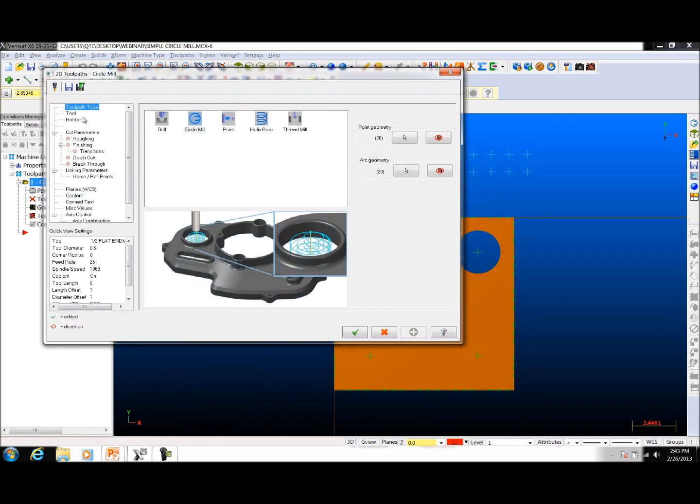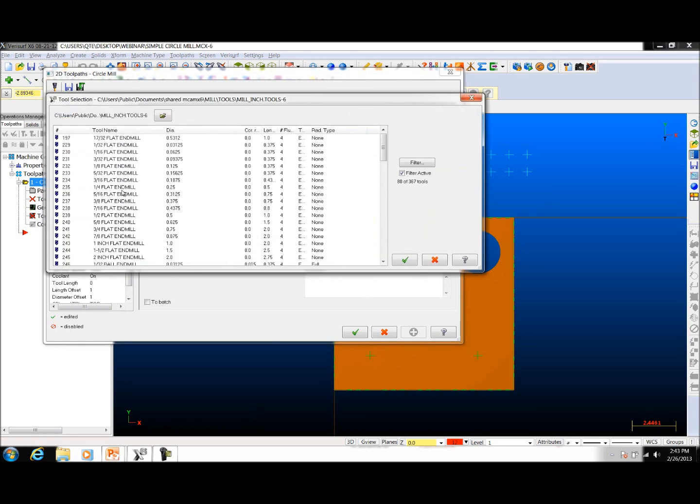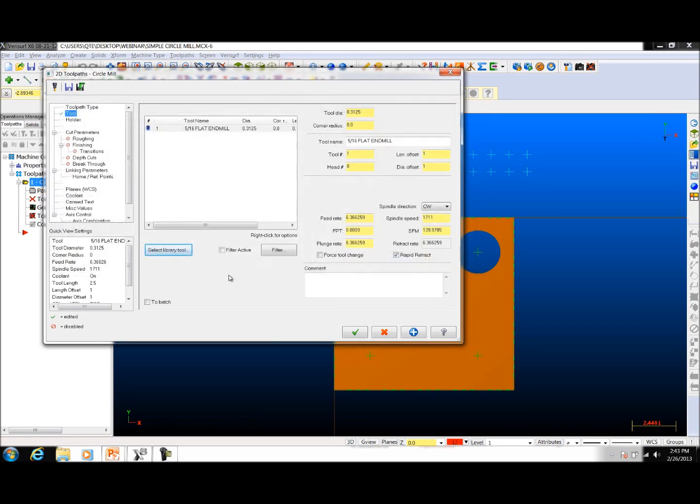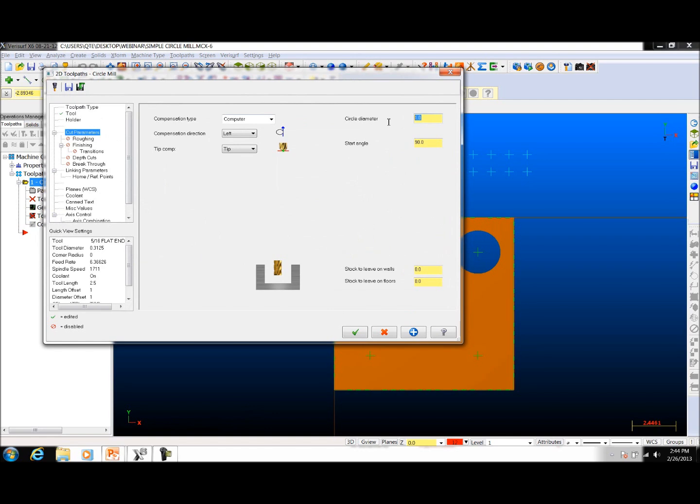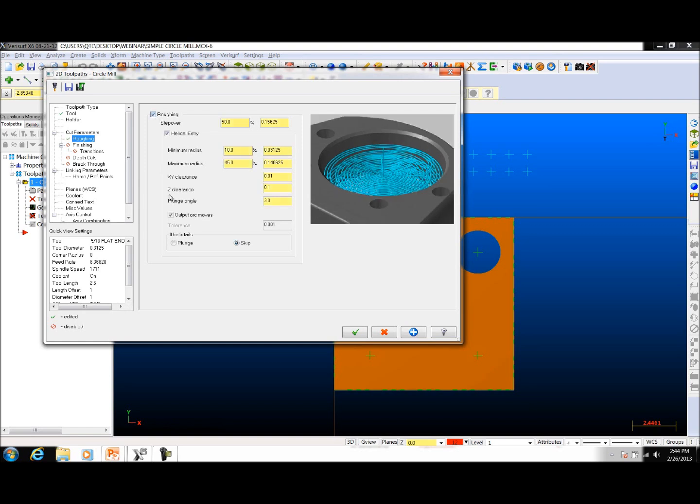Okay? Go pick a cutter. Now since there's no geometry there, it just has a location, I have to fill out every parameter, meaning what's the hole size? 750, 875, whatever the print requires. Now you can rough it out. Now if you use roughing, it'll use a corkscrew type spiral motion, starts from the center and climb mills to the edge of the hole. Okay, this is your step over. 25% of the tool, 50% of the tool, this is your choice, depending on material and the machine tool.